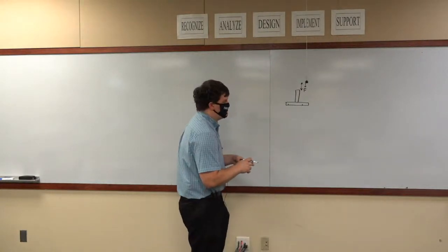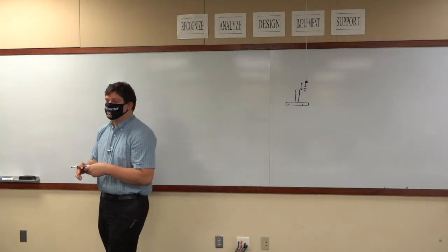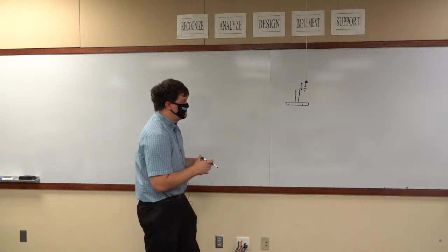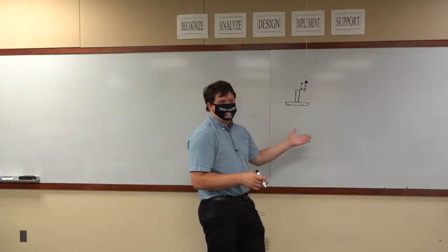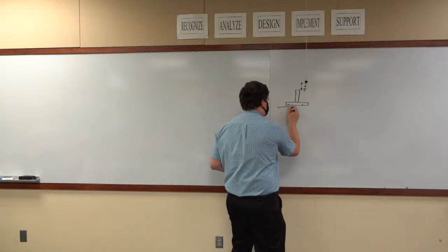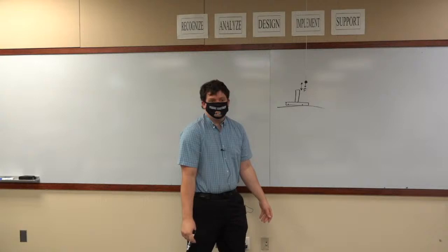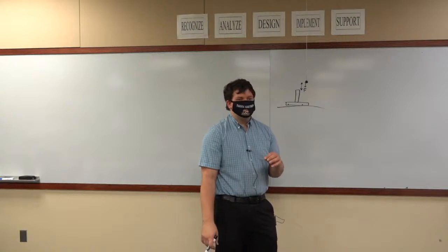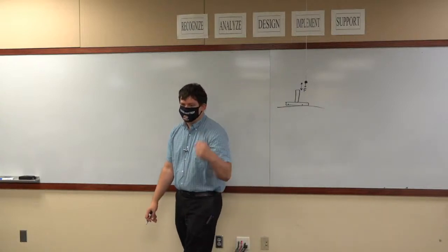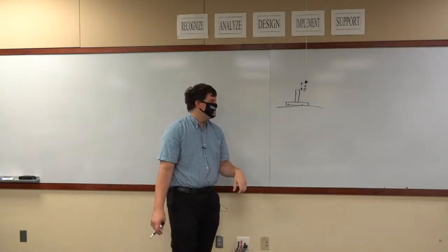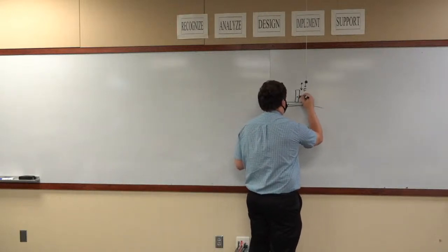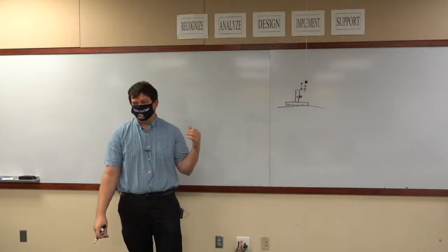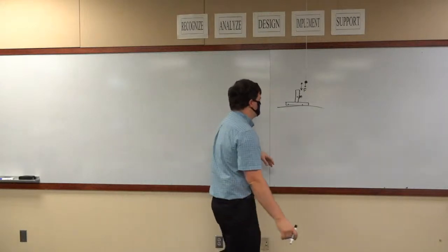And because we have a dynamic motion, something comes into play that really wasn't in play when we studied this in statics class. This is a really simple statics problem. If this is sitting on a piece of sheet metal and you apply some force, it's not hard at all. But it becomes a much more challenging dynamics problem. So you're just taking this thing and stamping it. This has some certain amount of mass, and that mass means that every time it moves, it requires a certain amount of acceleration.